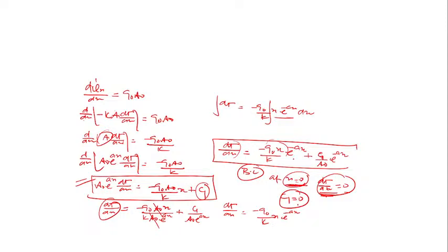So at x equal to 0, if I put in this equation x equal to 0 and dT/dx 0, then that is 0 and this becomes 0, this becomes c1 equal to 0. Otherwise, you can put here also at x equal to 0, x becomes 0, dT/dx is 0, and this becomes c1 equal to 0. So in the next dT/dx, I will not write this term. This term will be 0 because c1 is 0. Is this clear? And here if you further integrate, then I get the other constant called c2. Clear?